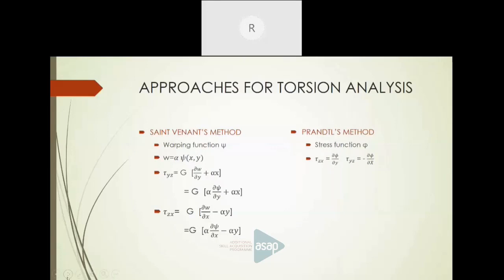So we were talking about the boundary conditions from the lateral side. From the boundary conditions on the lateral side, we got our first equation for solving shear stresses. Now we want one more equation. For that second equation, we go to the region, and we are going to derive the equation for torsion, because after getting shear stresses, next is about deformation. We have to make sure that the deformation is also within the safe limit. Deformation means angular twist here.